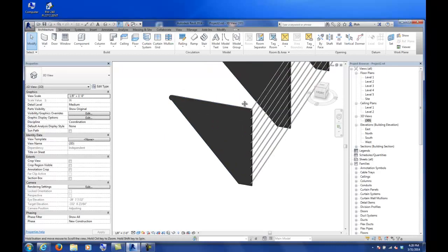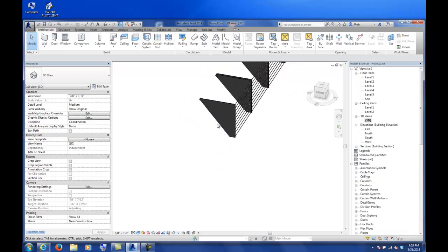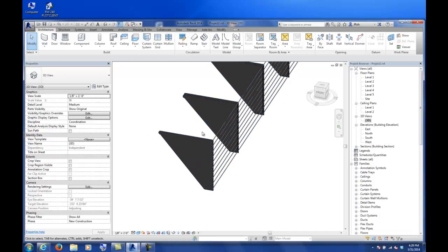Basically, whenever you make a baluster, wherever that top baluster reference plane is, it's always going to stretch based on the parameters of the railing. So we'll get that looking a little bit better in a minute. So I had to rotate it. We should have probably performed that extrusion in a front view instead of the left view, but it doesn't matter if you just rotate it around.